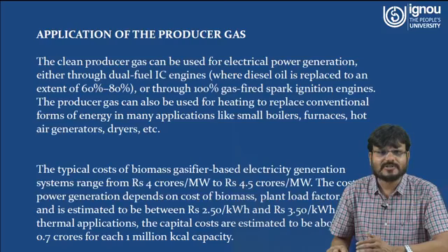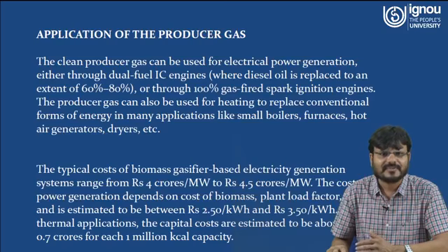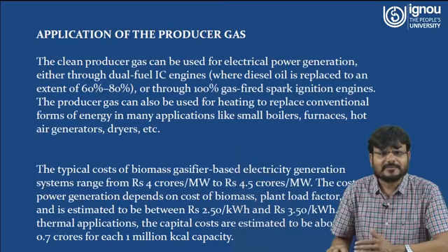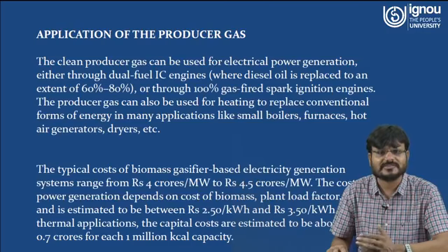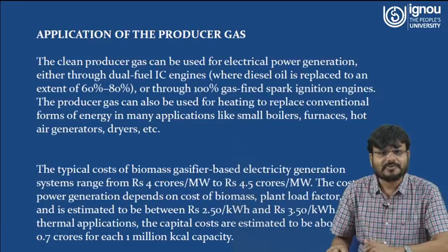Now we have to understand the application of this producer gas. The clean producer gas can be used for electrical power generation, either through a dual fuel IC engine where diesel oil is replaced to an extent of 60 to 80%, or through a 100% gas fired spark ignition engine. The producer gas can also be used for heating to replace conventional forms of energy in many applications like small boilers, furnaces, hot air generators, dryers, etc.